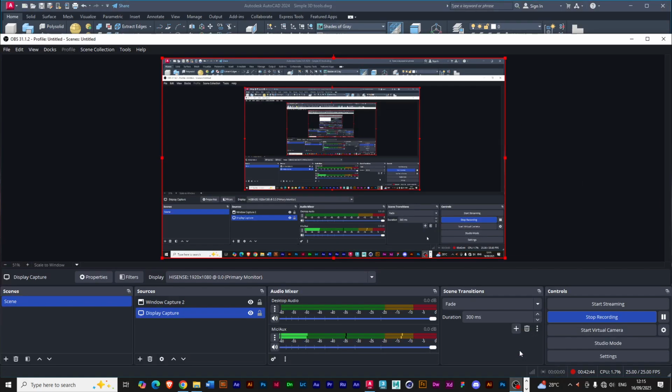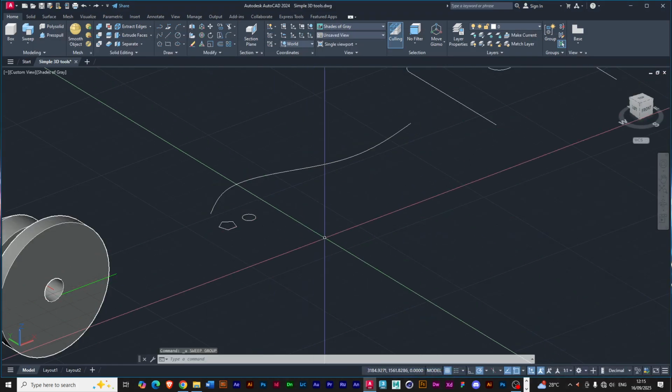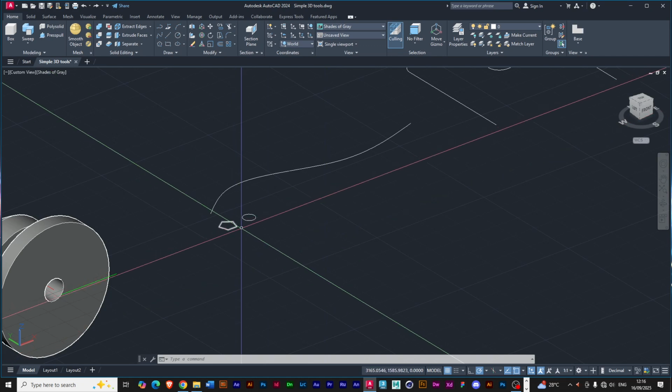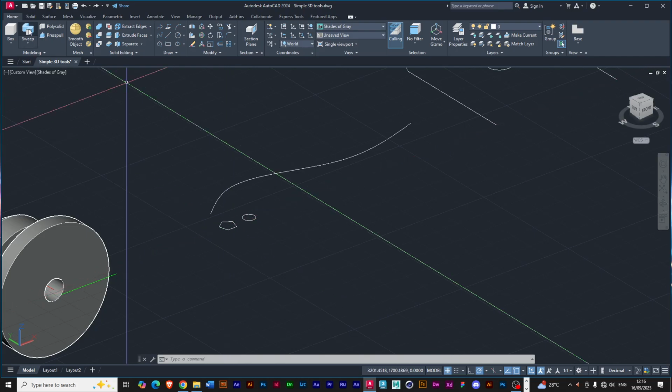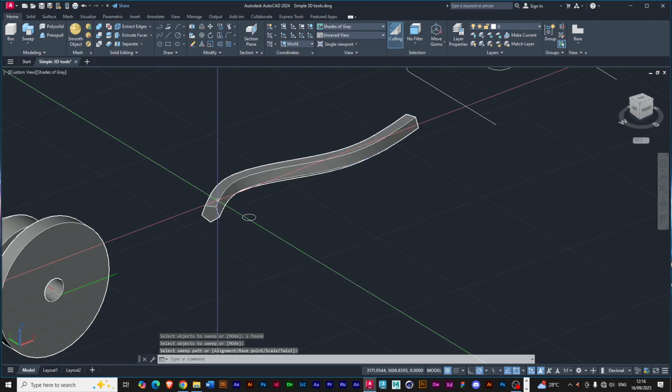You have swept the sweeper. Have you swept? Yes, that's swept. Okay. Yes, and then press enter because you have to always press enter. Then you now select the path you're sweeping it along. So if I'm sweeping this polygon, select the sweep, I sweep this, select this guy, I press enter, and now sweep on this path, and the object automatically goes.